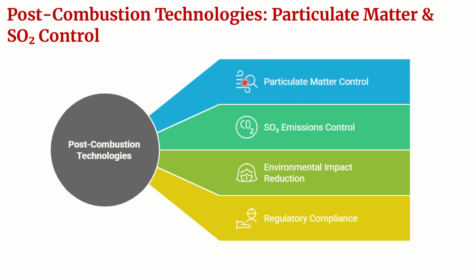So this involves the application of electrostatic precipitators or fabric filters. The flue gas passes between electrodes. Dust particles are negatively charged and then attracted to positively charged collection plates, which are periodically rapped to dislodge the dust into hoppers, which yields higher efficiency for fine particulates.